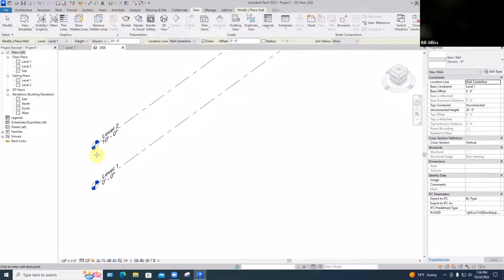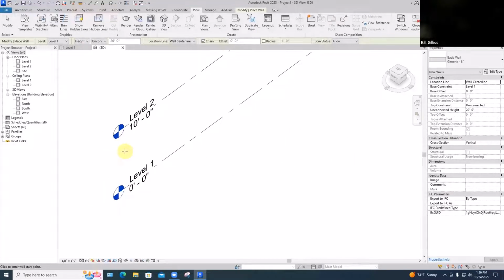So over here, I'm going to call your attention to the main conceptual difference between how Revit organizes space and how AutoCAD does. AutoCAD has that 0,0,0 point, which is down on the floor somewhere, and everything is in relationship to that. But it has no real way, unless you do them side by side, to do first floor and second floor, like we've done for Schneider Hall for Molly's class. The way it gets around it is you do the basement in one CAD file, the first floor in another CAD file, and you reference this one into this one, then you have 2 of them stacked in another drawing.